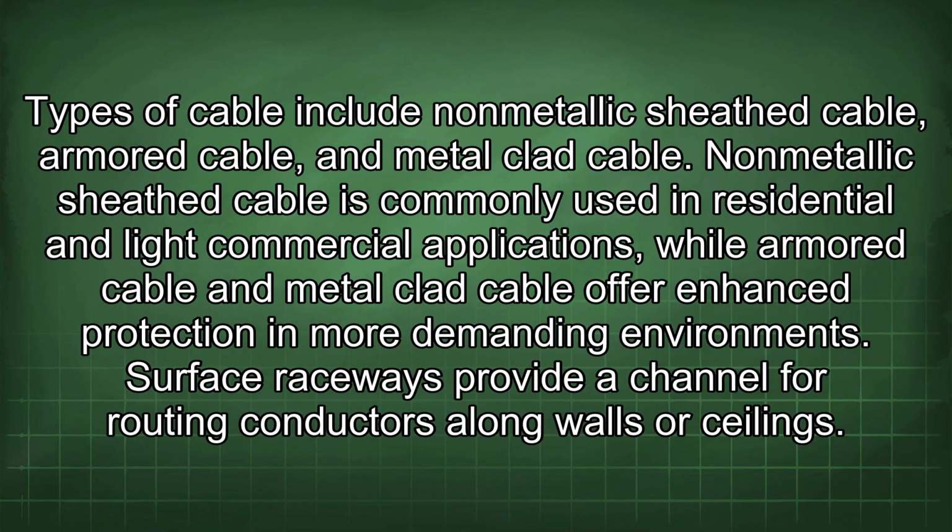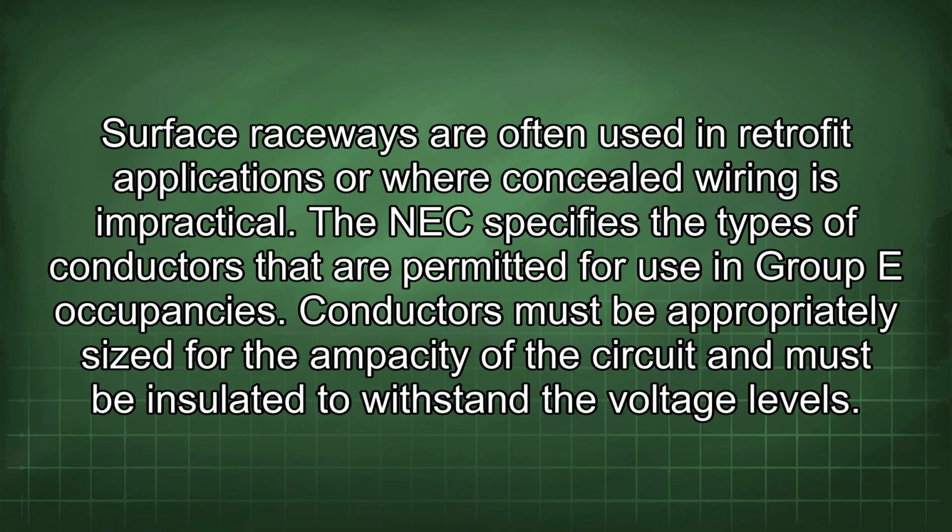Surface raceways provide a channel for routing conductors along walls or ceilings. Surface raceways are often used in retrofit applications or where concealed wiring is impractical. The NEC specifies the types of conductors that are permitted for use in Group E occupancies. Conductors must be appropriately sized for the ampacity of the circuit and must be insulated to withstand the voltage levels.